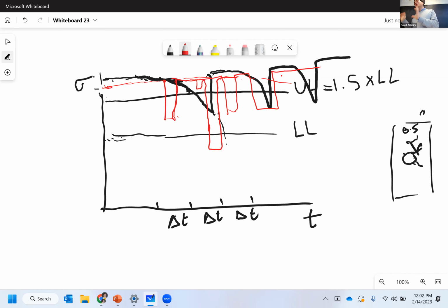So it's basically for metal, we don't have this, but for composite, since we are not sure about the nature of impact, there's a bit of crack in the material. You have to show that for a life cycle of the structure, that size of the impact zone doesn't grow. It stays the same size. And it lets you catch it in the next interval, repair it, and bring the structure back to its full performance. But I'm going to talk about this repair strategy and no crack growth approach for composite. Any questions on the impact of composites and then fatigue in metals?